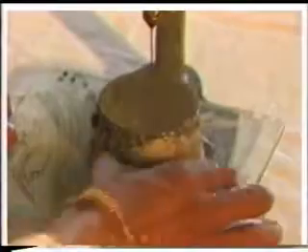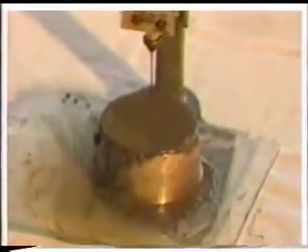Place the test block under the needle. Lower the needle till it comes in contact with the surface of the test block and gently release, allowing it to penetrate into the test block and observe penetration. Repeat this step at appropriate time till the needle fails to pierce the test block 5 to 7 millimeters from the bottom of the mold, and note this time.